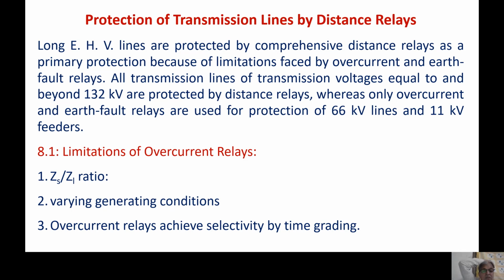So to discriminate between these two fault locations becomes difficult. Whereas if you go for distance protection, what does distance protection do? Distance protection works on the principle that it measures the local voltage. Local voltage means if I have to protect the line from Ahmedabad to Baroda, I have to measure voltage at the Ahmedabad bus and local current, that is the Ahmedabad to Baroda line current,